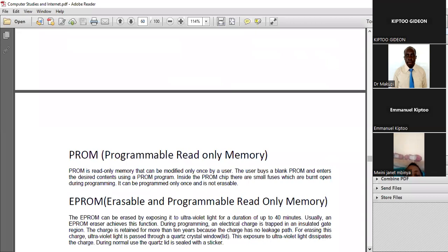So you see, at the end of the day, I've created a pattern 1 0 1 0 1, which equals 21 in that regard. So that is an instruction in a computer. So when you burn the fuses, it is putting in instructions. Now, the drawback of this one is that in case you burn accidentally or reprogram it wrongly, then you just throw away that PROM chip.